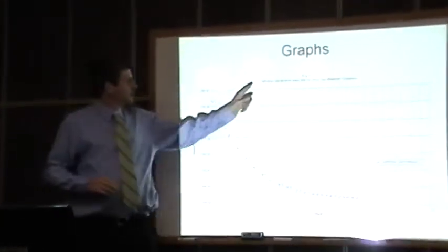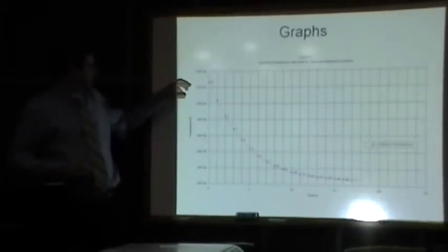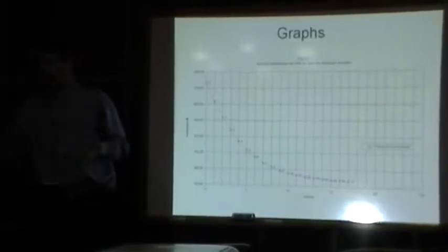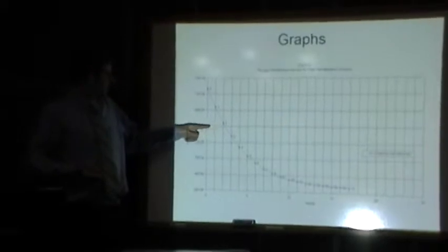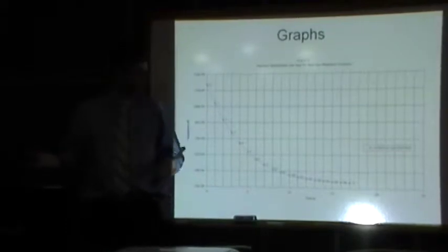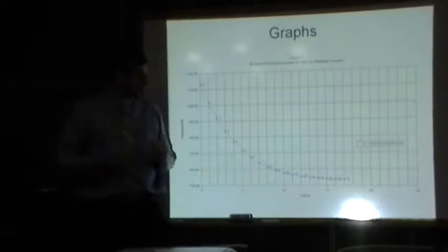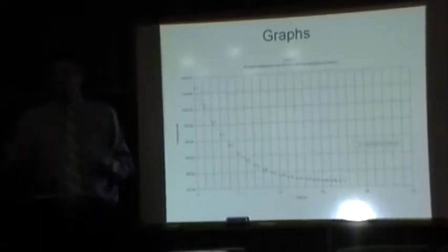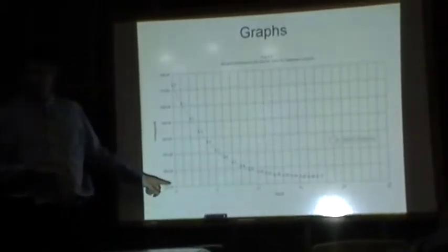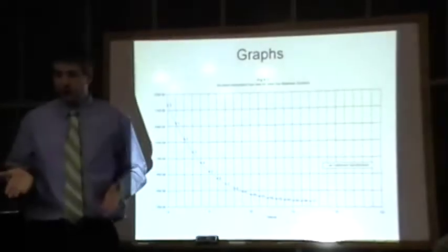So here is the temperature of the beryllium for an isothermal blowdown scenario. At time t equals 0, it's at 1200 Kelvin, which is what was given. And then as we step down, it makes a nice gentle curve, which is expected for an isothermal blowdown. By about 13 seconds, we're starting to lose a lot of heat transfer, as a lot of the heat has already been transferred out of the core. The temperature of the beryllium is around 300 Kelvin, and by 17 seconds, it is essentially a cold gas jet.